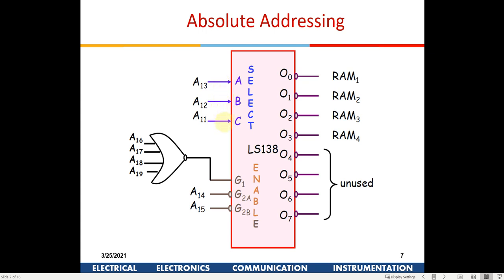So in this case, we have designed this for 4 RAMs, and you can keep one more slot open, right? And then you can give the same inputs to that RAM also, right? If you keep one more slot, the same A12, A11, A13, and then you keep these also there in one more slot, and you don't push a RAM there.